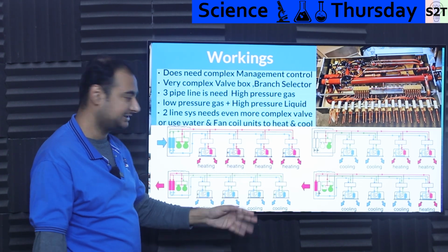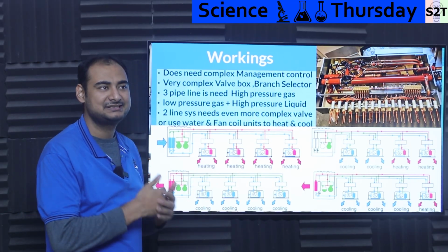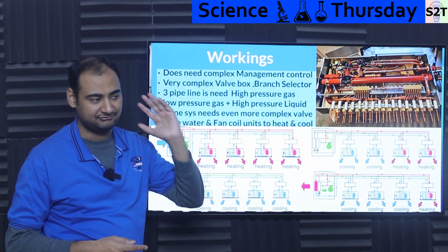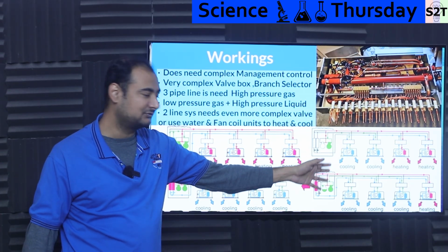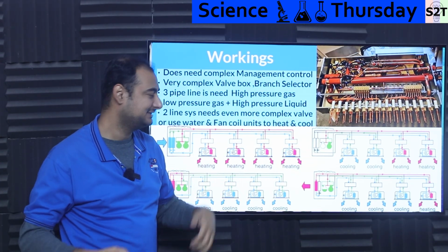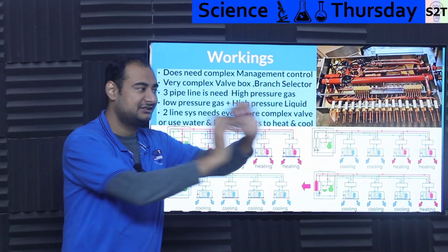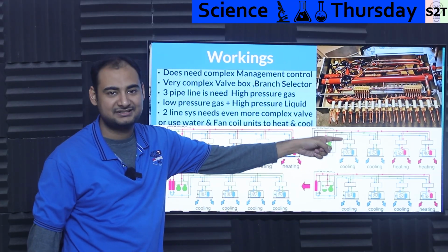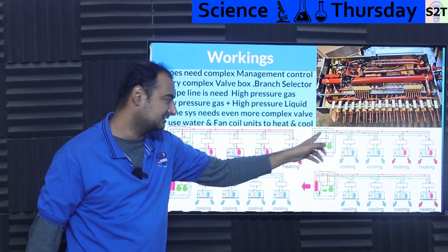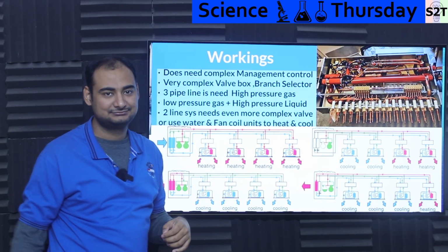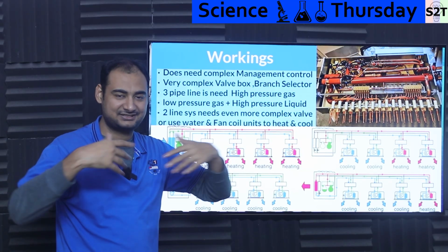Now here's the deal. You have to balance it. Realistically, you will barely be in an all cooling or all heating scenario. Many times when people are doing this, they need that odd scenario where one has to be cooling and one has to be heating. This is the optimum scenario, where the amount of cooling, meaning the amount of heat you are leaching from point A, exactly matches the amount of heat you need for another place. So you take heat from here and dump it there. In that scenario, all the refrigerant is circulating inside. It is not touching the outdoor heat exchanger. It is circulating from one unit to another. The compressor is still working, but it's circulating from indoor to indoor. You have an AC here and a condenser here. That's all you are doing.